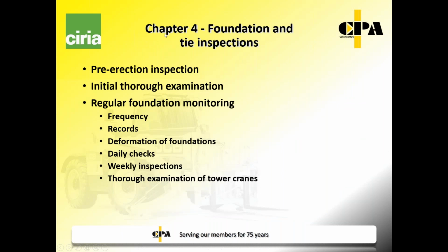And then the final chapter before one gets to the appendices is foundation and tie inspections. So we're talking about the pre-erection inspection, so that you make sure that the base or the tie sites and so on are ready to put the crane up. Then after the crane has been erected, you have an initial thorough examination just to make sure that the whole system has the required integrity.